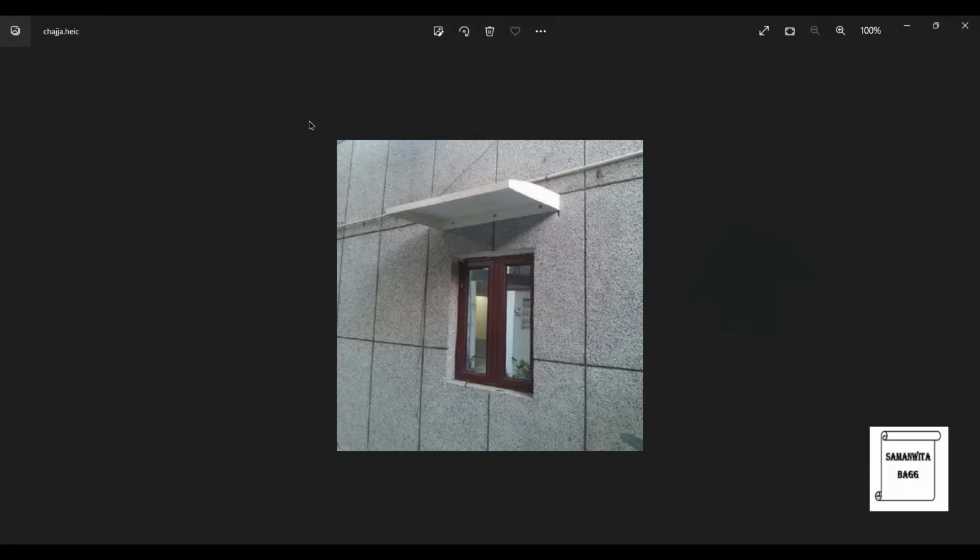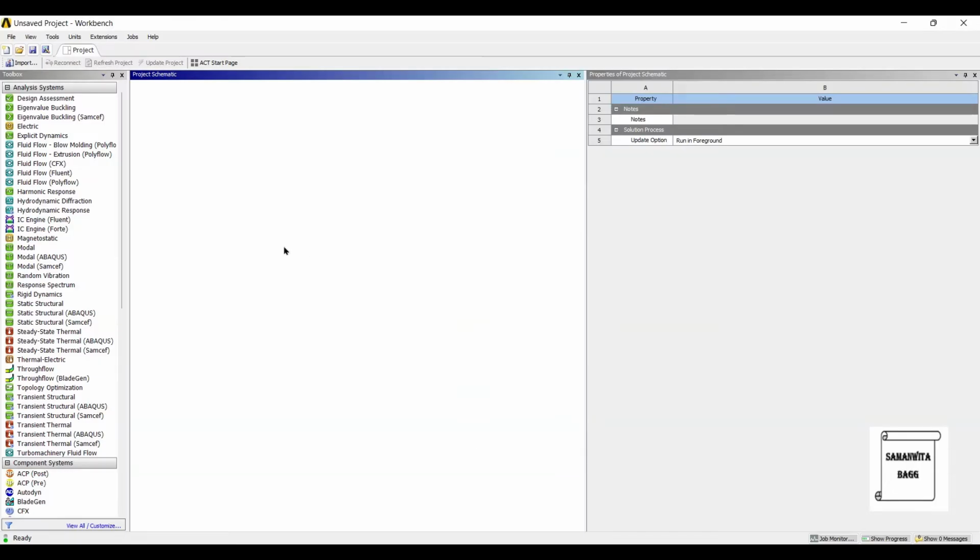And suppose the amount of load is zero at that end, then we can say there is a very minimal requirement of material on this side. By numerical calculation in the strength of materials subject, you can go through the videos and you would understand that the maximum bending stress is generated at the end connected to the building. So let's analyze this overhang beam, sunshade or chajja, for its topology optimization.